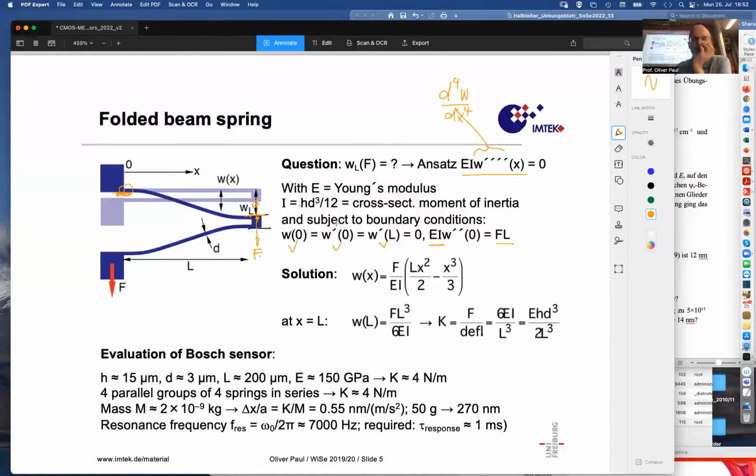So here we have these 4 boundary conditions which we try to solve, and we do just an ansatz where we say W0 is equal to constant 0 plus constant 1 times x plus constant 2 times x squared. How far do we have to go? Well, we can go up to a cube. The 4th power we can't have, because then the 4th derivative wouldn't be equal to 0.